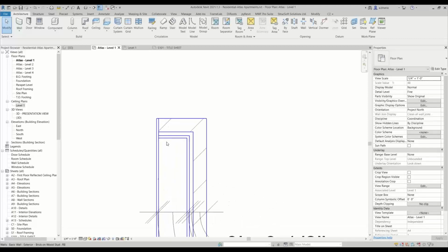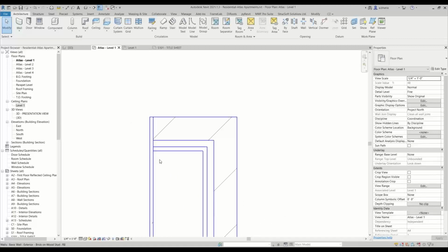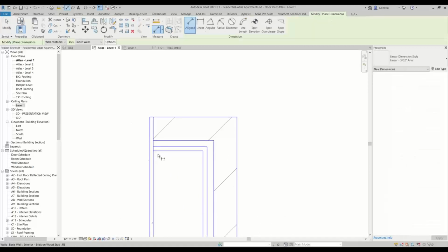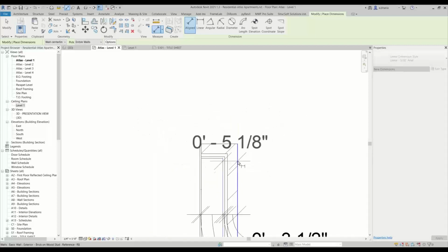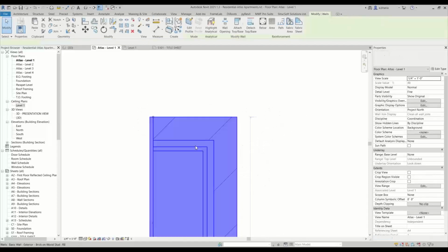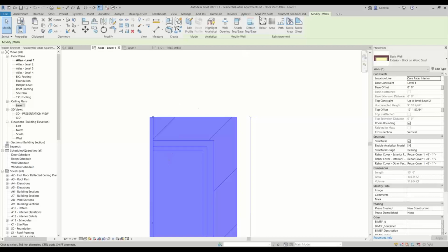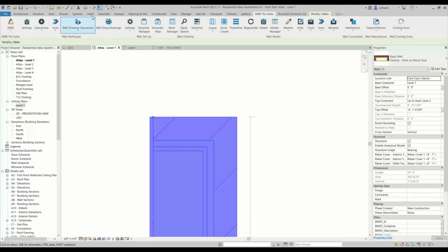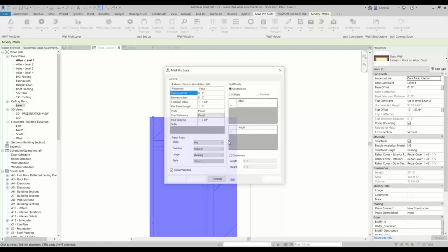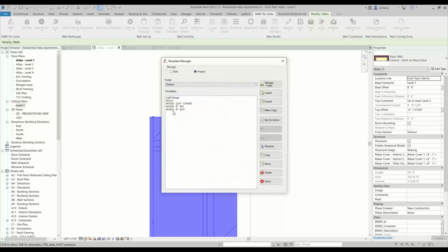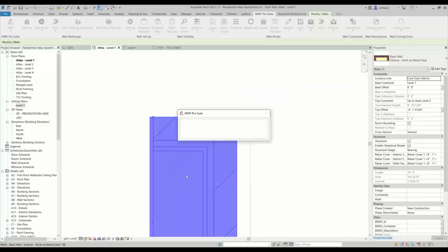If you did want your panels to be cut short and you know that this is the wrapping condition every single time, you could basically do the dimension from here to here. So that's 5 1/8. And you can have your panel cut short by using either the join conditions, or I'm just going to quickly create a panel that is active, close, create.